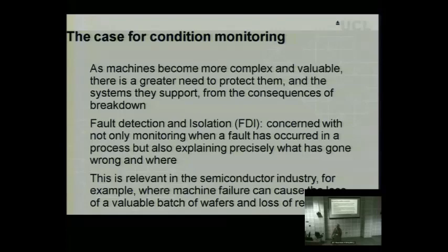Well, it depends on the unknown input observer. I'd say if your unknown input observer was a sliding mode one, yes. If it's a different sort, then you're not going to get exactly the perfect tracking, because you're not going to be able to force things to zero, other than if it's a high gain unknown input observer. To get the same performance from an unknown input observer as you would get from a sliding mode observer, you would need infinite gain.